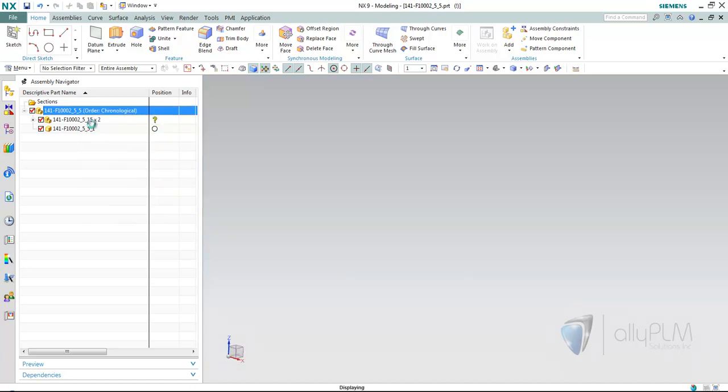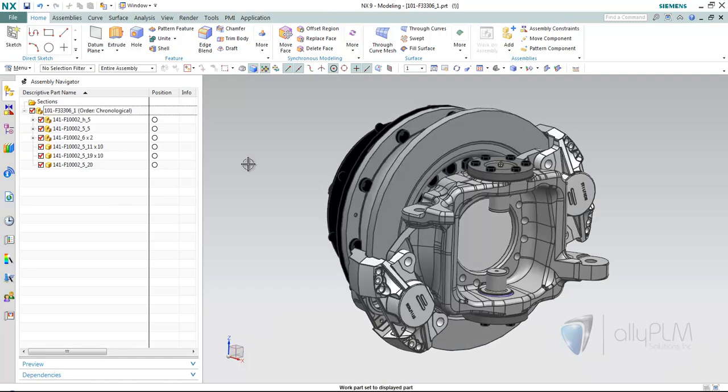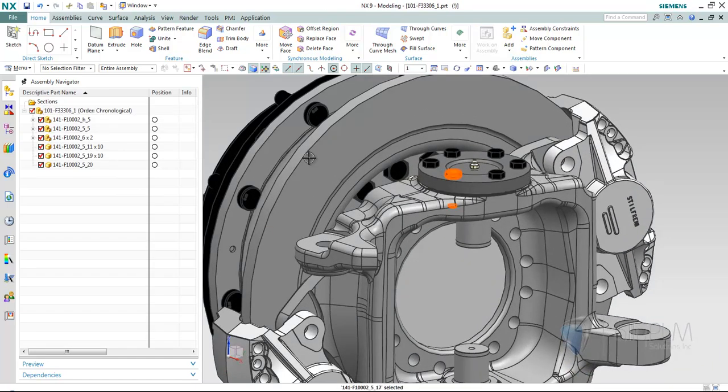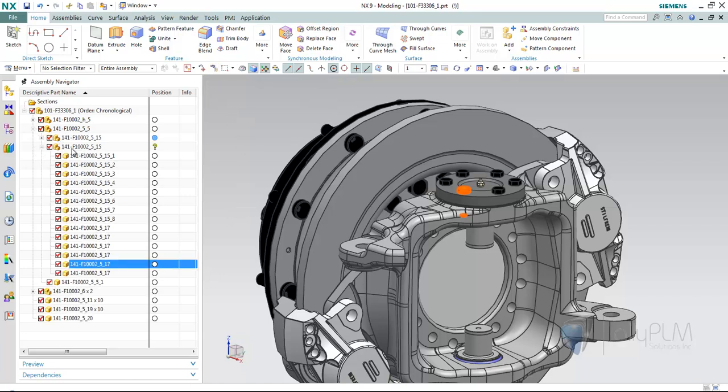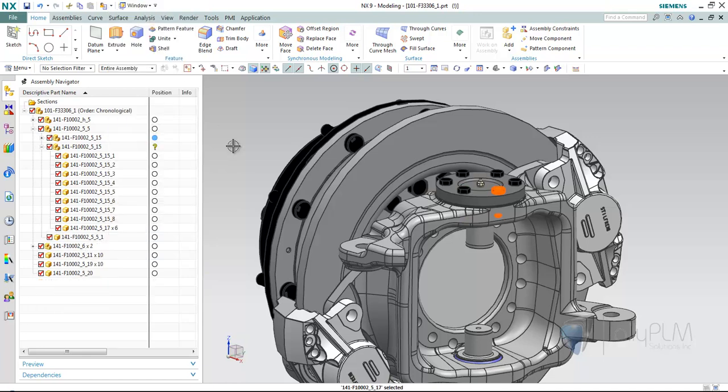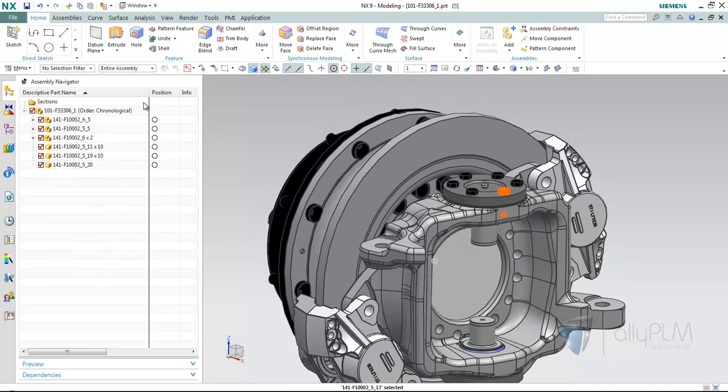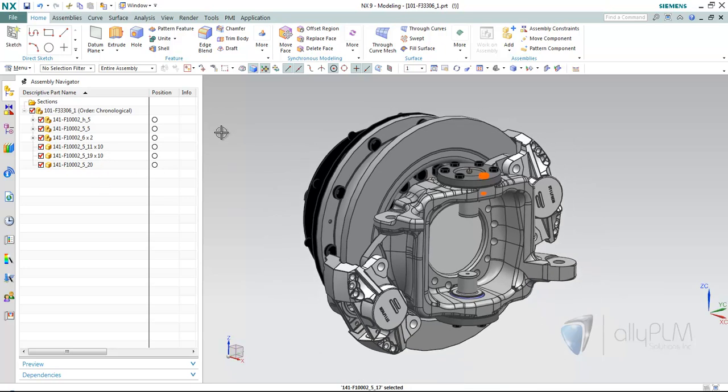So I'm going to go back to my top level assembly. Also some behavior here. If I look here at one of these fasteners, I have no idea if it's in a sub level or whatever, but if I use my find in navigator, it's obviously expanding the subassembly, but it unpacked that at the same time. So I didn't have to go in, find the subassembly, and then unpack it. If I right click whenever I'm done, I can pack it back. So just to make you aware that based on our customer default option, whether it packs assemblies on file open, that's why you're going to notice that those particular assemblies are packing on file open.